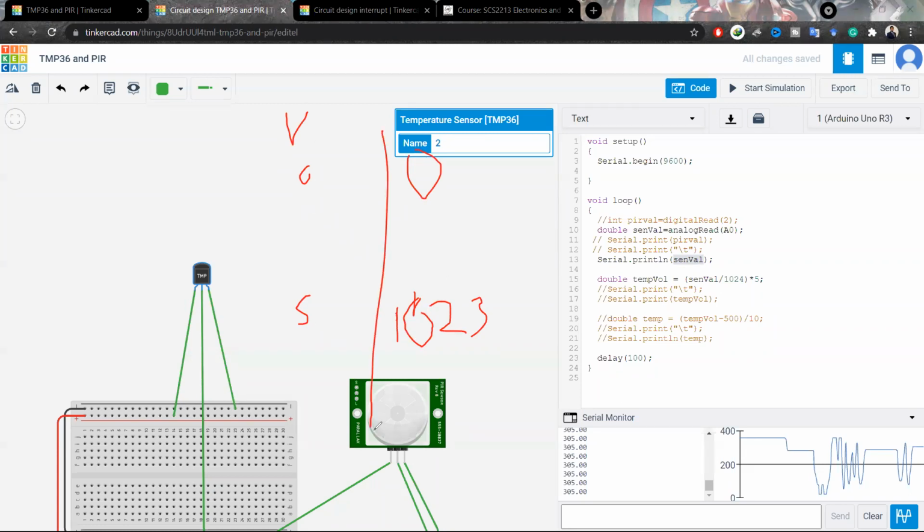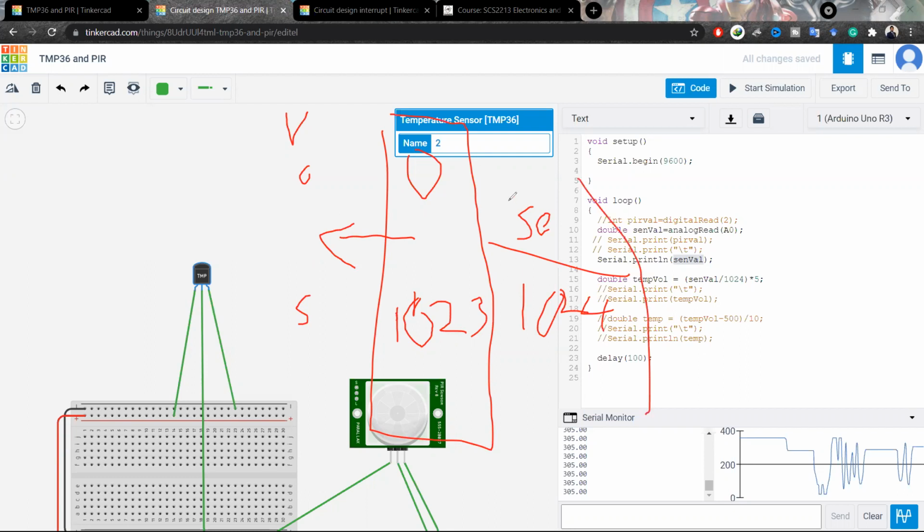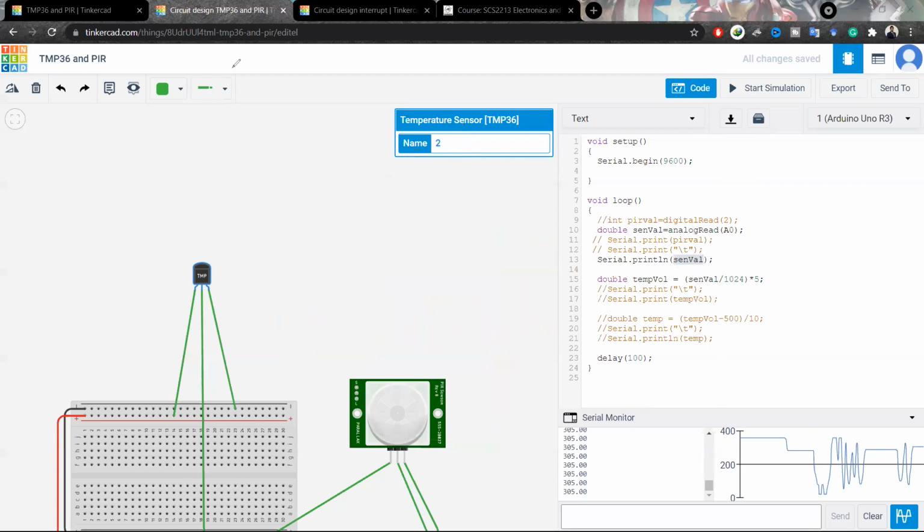So you are reading some value from this part, then I need to translate it into a voltage value, right? So you can get the sensor value, whatever the sensor value is, and the maximum value is also 1024 here. Sorry for my bad writing. Then you have to multiply it with the maximum voltage 5, right? By doing this, you can get the voltage value. In the voltage sense, but for this sensor, we should deal with the microvoltages. That's why initially it was 5,000, right? Okay, if I run this thing,